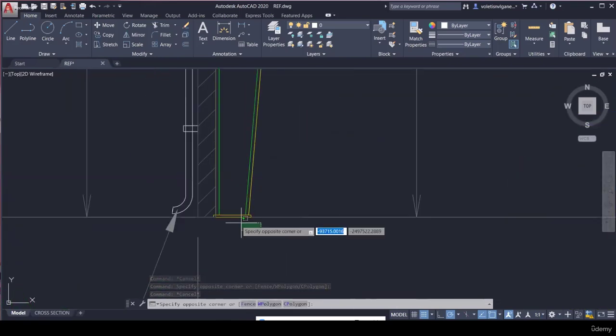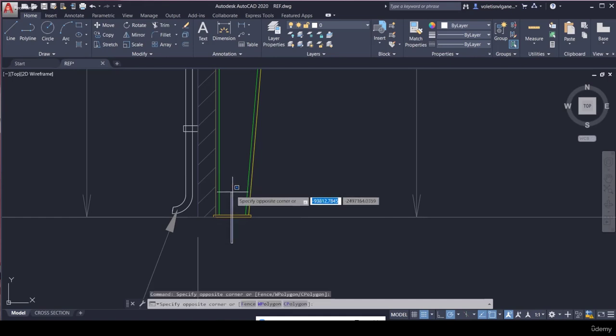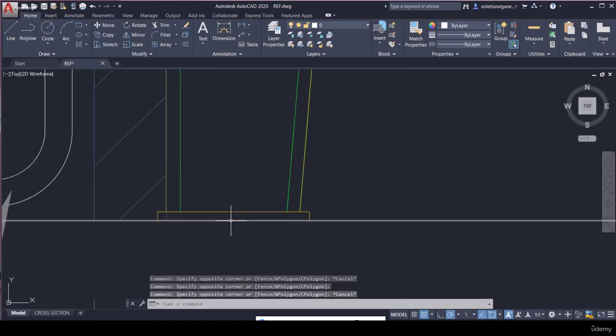First, you have to assume the base of the column. Generally, for simple buildings, it will not be more than 300 or 350 or 400. Generally for a pinned base, it may not be much more than 400. So you have to assume that in your mind. So for 400, the center line will be 200, right? So the STAAD line will take from here only. Node will take from here only.